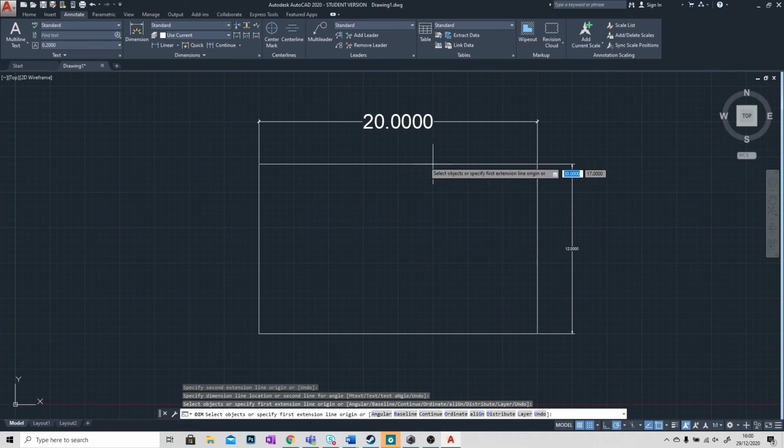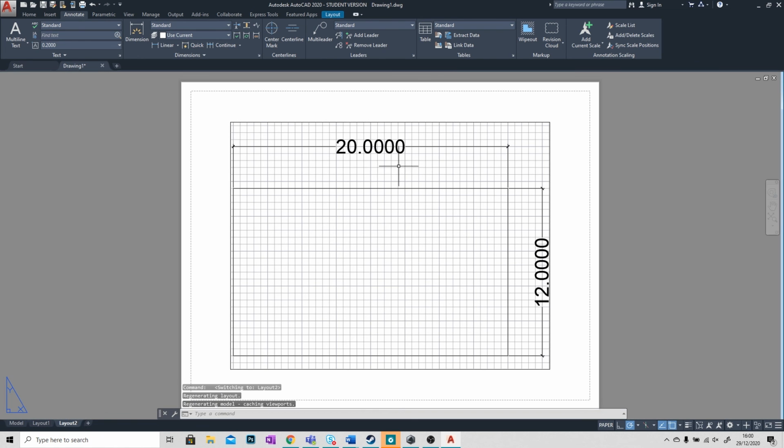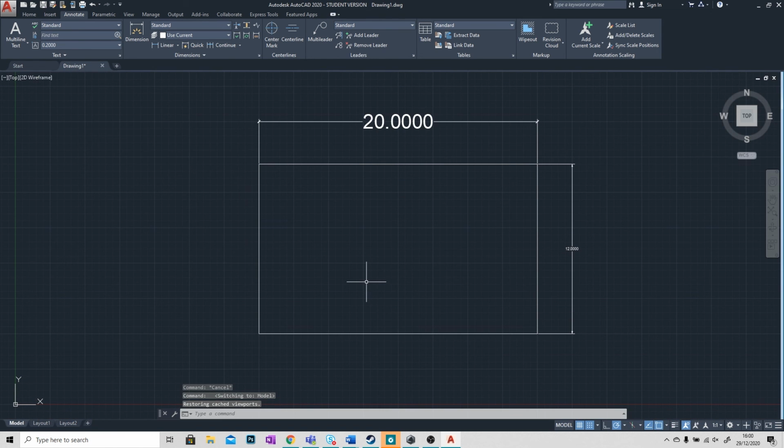If you want to see how this will look on your printed document, of course, if you're printing off your image on A1 and 1 to 50, all that kind of thing, then go down to the layout panels at the bottom here, and you'll be able to see how big the text is on the paper. Okay, and then of course you can just jump back.